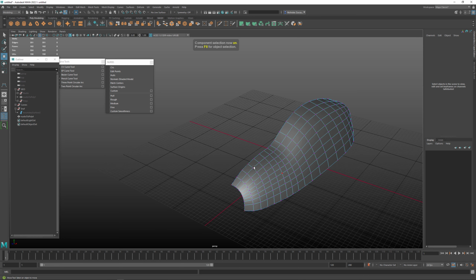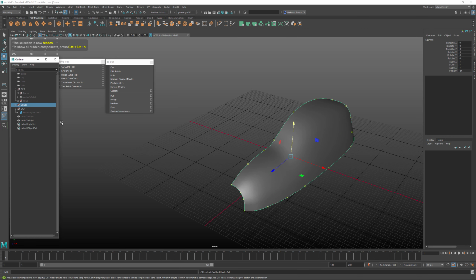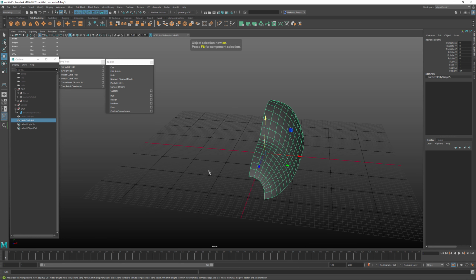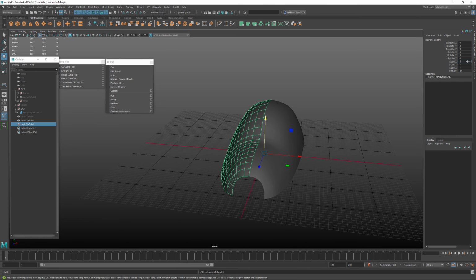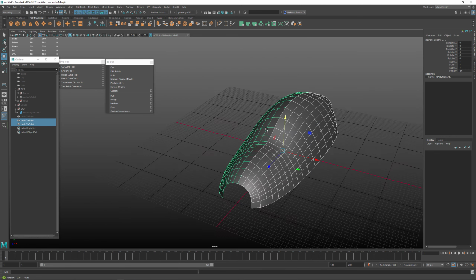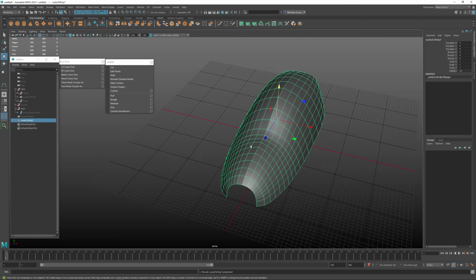And so what I'm going to do, I'm going to take this NURBS topology, and I'm just going to duplicate it. I'm going to hide this one here, and I'll hide the curves. And if I built everything correctly, I should be able to duplicate this. I'm going to hit Control D again, and then give it a negative scale in X. And then everything should snap up. So I could take these two surfaces like this, and then just go Mesh, Combine. And I'm going to delete history on it, Alt-Shift-D.